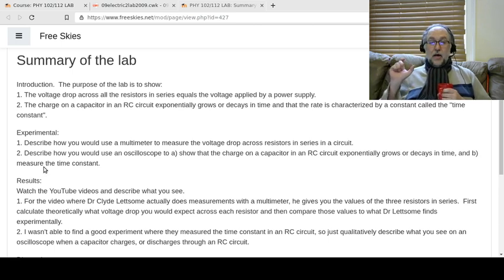And I have a YouTube video which is specifically aimed at that. Now there's a lot of information in that, so you really want to key in on how it's done, without actually doing a numerical example. You basically have to pick two times, and there are two voltages at two different times, and by fitting the exponential to those two voltages at the two different times, you're able to get the time constant. And he does that in that video.